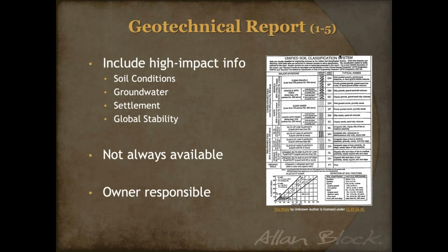Now, moving on to the geotechnical report, I want to start off with a big positive here. Lately, we've been seeing that a lot more geotechs are getting involved early on in the design phase for a retaining wall, and that's something that is so important. I can't stress it enough. When that geotech gets involved early on, we're able to get a geotechnical report, a soils evaluation, all of that right at the beginning of a project. And when that happens, a lot of those factors, that's soil conditions, groundwater, settlement, global stability, all of that has a high impact on our wall stability and how our wall will be designed. So the sooner we can get that, the sooner we can come out with accurate designs.